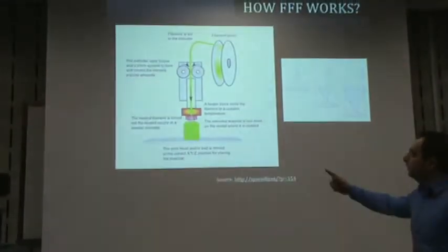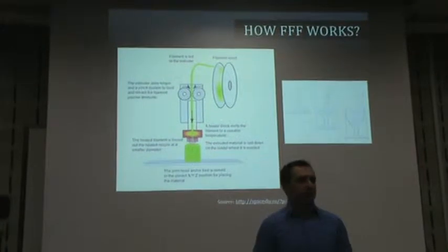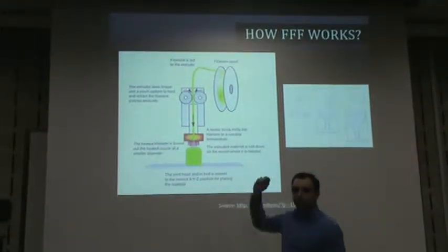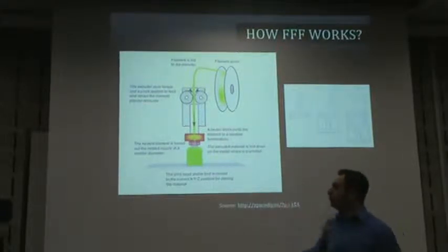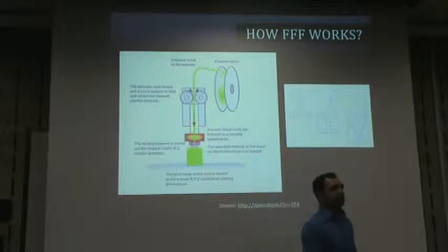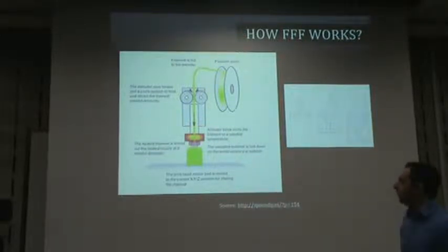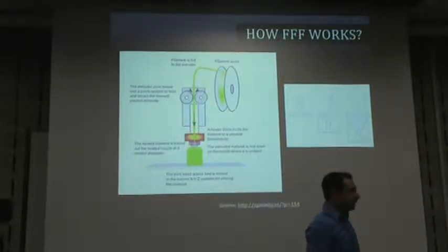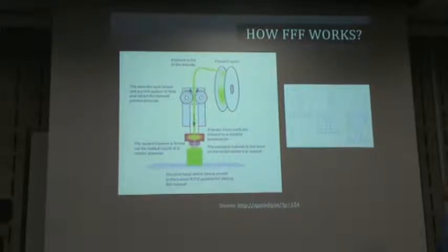So here's an example of what the extruder looks like from the inside. You have the spool of material, and that's driven by two motors. As the filament comes through the nozzle, it will be heated up, depending upon what material you're using, PLA, ABS, or whatever it is, and it will be deposited in an XYZ location, wherever the printer's STL file tells it to. So you have taken a look at the vase that we built.